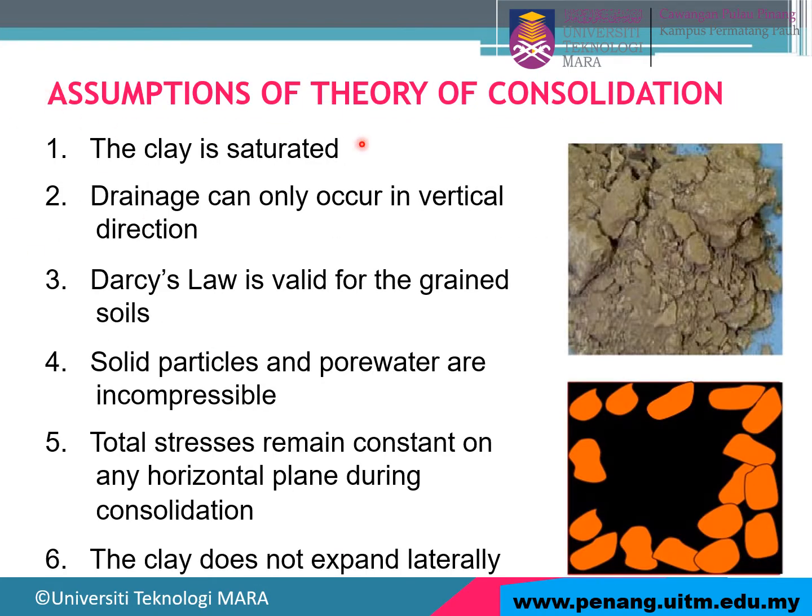So for the theory of consolidation, we assume the clay is saturated. Drainage can only occur in the vertical direction, at the top or bottom. Darcy's law is valid for granular soils. Solid particles and pore water are incompressible. Total stresses remain constant on any horizontal plane during consolidation. The clay does not expand laterally. This is the assumption of the theory of consolidation.